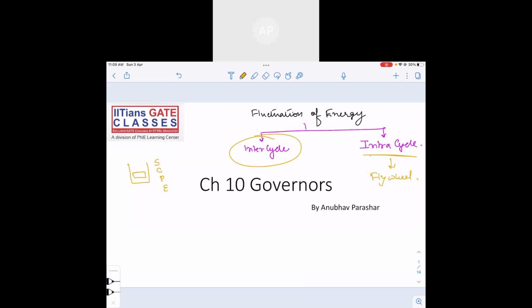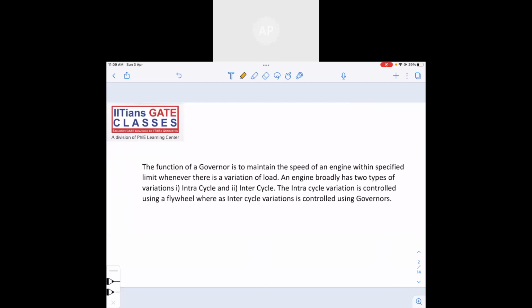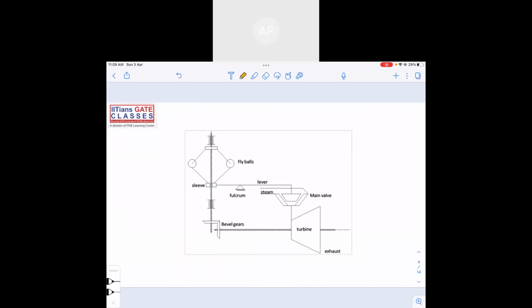Lunch hour, automatically all the machines will get shut down. Suppose there are a lot of factories or industries, all the machines during lunch hour will get stopped, so the power consumption will suddenly decrease, and after lunch again it will increase. Evening time again you will have a tea break, again it will decrease, again night it will be switched off. So continuous fluctuation of power requirement is there, right?